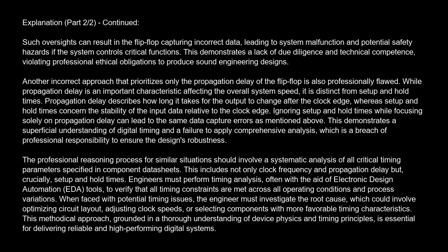The professional reasoning process for similar situations should involve a systematic analysis of all critical timing parameters specified in component datasheets. This includes not only clock frequency and propagation delay, but, crucially, setup and hold times. Engineers must perform timing analysis, often with the aid of electronic design automation (EDA) tools, to verify that all timing constraints are met across all operating conditions and process variations.